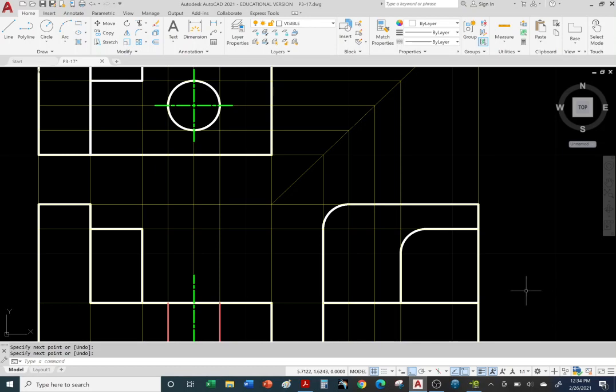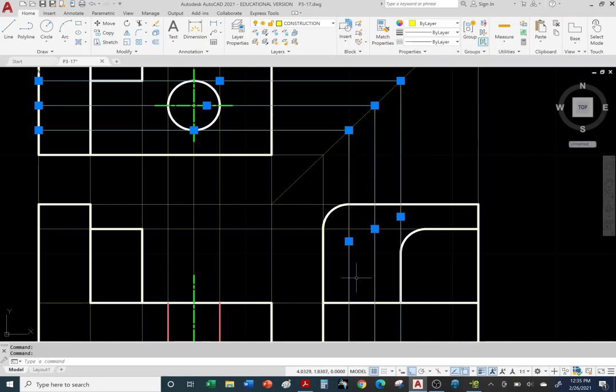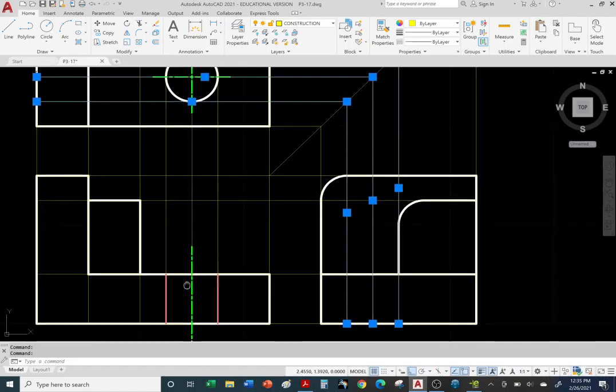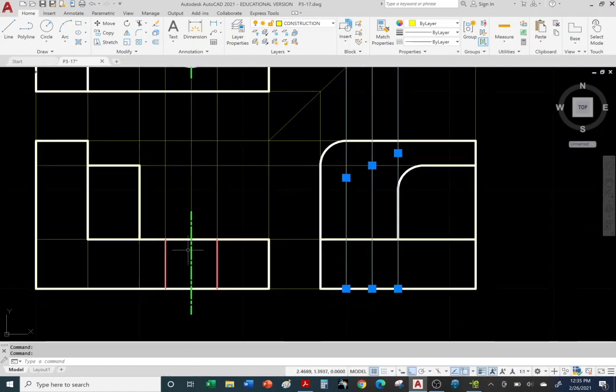Okay, so let's go back. We're going to use these yellow construction lines to help us locate that hole into the right side view. But I've decided we're going to cheat. Instead of doing it the long way and having to locate the hole with respect to the top view and the 45, we can just copy the one from the left side view.